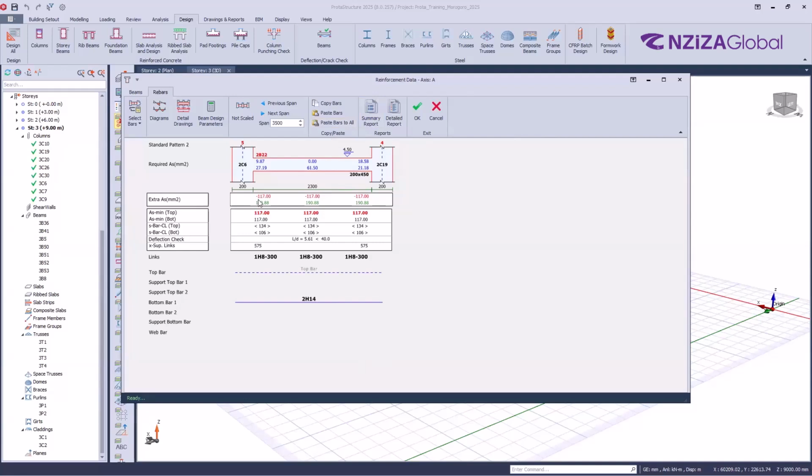So by viewing these numbers in red, I will automatically know that I have an issue of reinforcement. Okay. At the top side, because those numbers which become red are on the top. So it means the reinforcement issue is on the top. Then I can come manually and add top reinforcement.